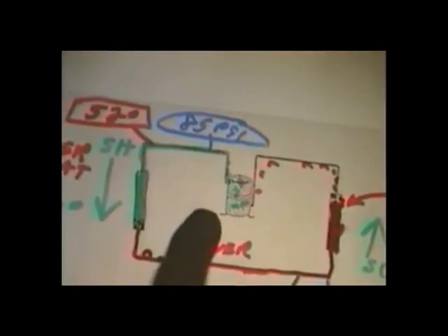Here it is. Overcharge, superheat low, subcooling high. Let's go look. Superheat low, subcooling high with an overcharge. Come on back over here. Overcharged. Superheat low, subcooling high. Same thing. Go to the next one.